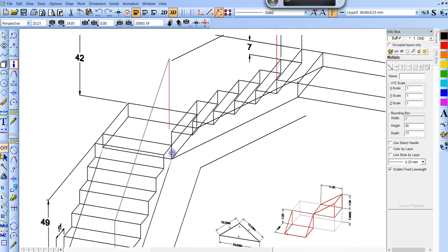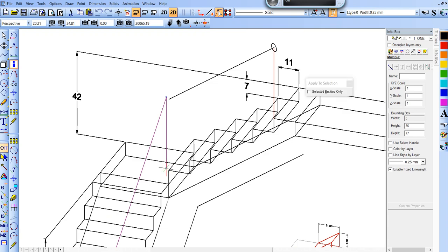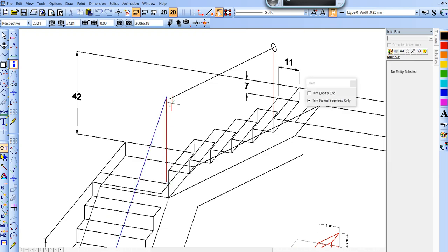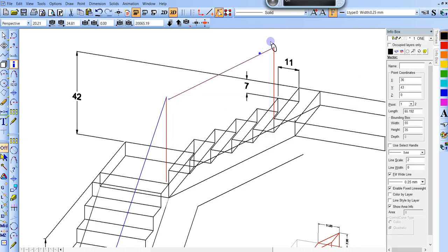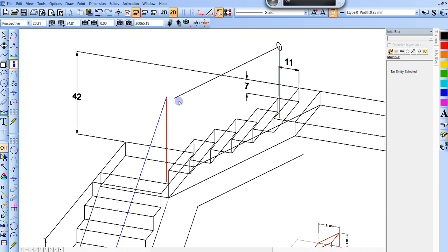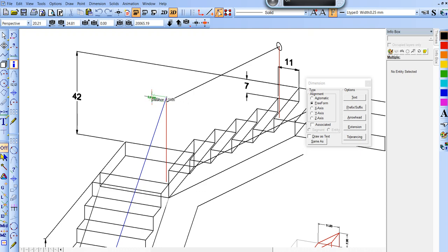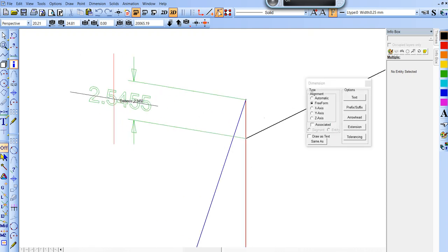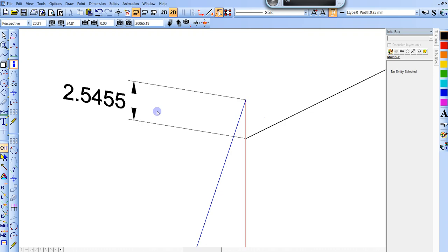All right. Now let's trim that so it's down to the landing. And then this, we won't trim into that yet, but let's do this. Let's take that too. Put this here. Control H. And then go up to that point. Enter. Like that. Enter. So that's 2 inches in each direction there, and then this should trim out to that. And now you see what you've got is a bust there on the height. A 2.5 inch difference in height.